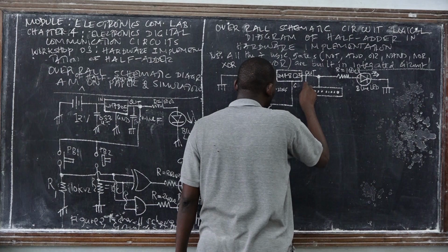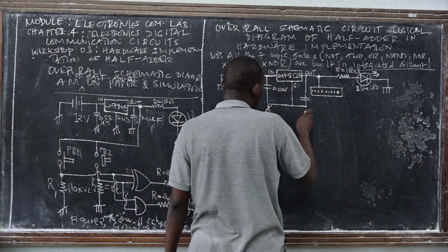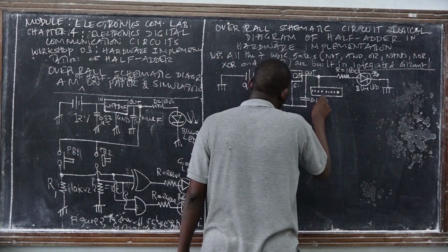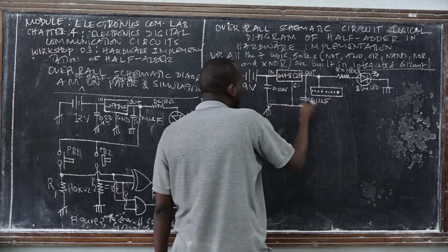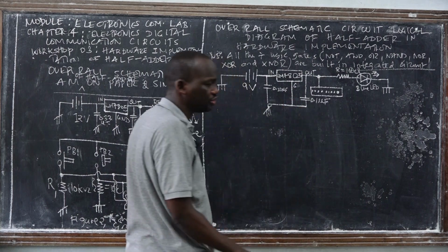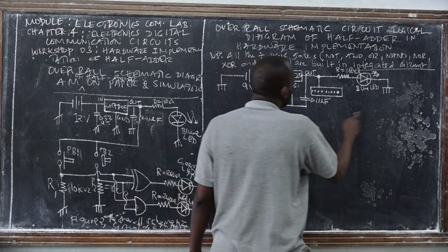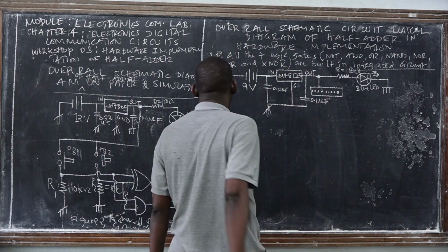But at this point, we also have another ceramic capacitor to stabilize, 0.1. Why should we connect these capacitors? This is according to the data sheet, or manufacturer's data sheet. Okay? Then we have our power bank at this point.